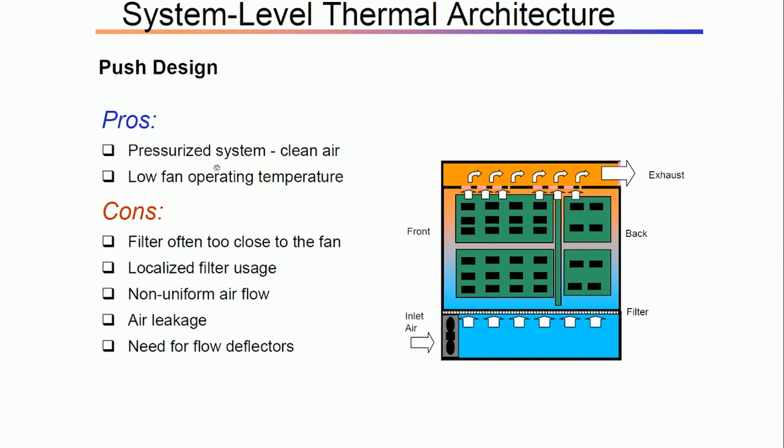Pressurized system, clean air, low fan operating temperatures. You understand, in the case of the push design, the main thing is you directly direct air, and the fan itself is seeing ambient air which may be cooler than the exhaust air, and a very very important thing in the whole system is that the whole system is under positive pressure. You have seen that if you go to most clean rooms, they adopt that system. This whole chamber is positive.